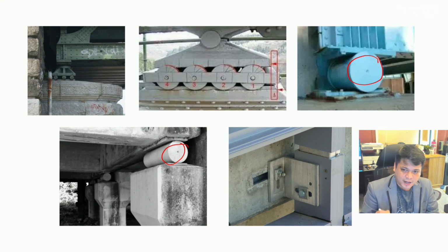Now, this fifth one is not necessarily a roller, it is not a wheel, but imagine that your beam, this is our beam, just a sample, will try to move in these directions. Because of this so-called slotted hole, what happens is it will just tend to move without reaction. So it is somewhat free to slide. It means, in actual, that is a roller support, but in drawing, we put the symbol here. So we have that kind of roller support.